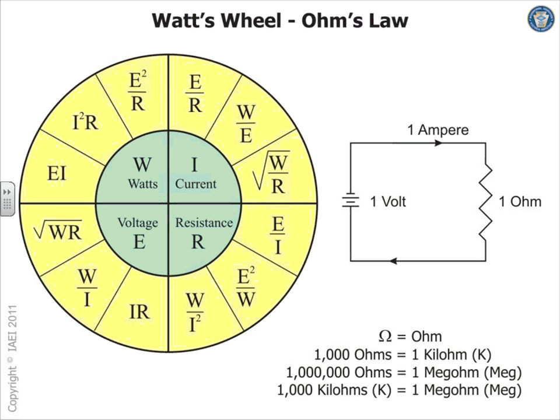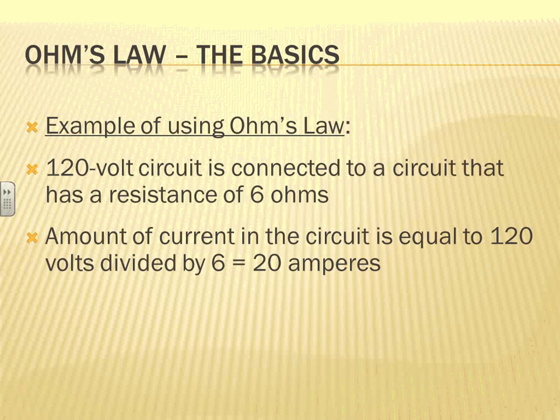What's the problem with this system? Number one, it's not efficient. Number two, it's not safe, obviously. So all we really need is one wire and the return of the system through Mother Earth. To make the system efficient, they created another wire, which got you the neutral. And to make it safe, they added a third wire so they can tie to all the metallic objects. In case any of these ungrounded conductors accidentally touch these metallic objects, that would be a disaster waiting to happen. So if you have a third conductor that you can tie all these metallic objects to the ground rod, the overcurrent protection device will be able to trip.